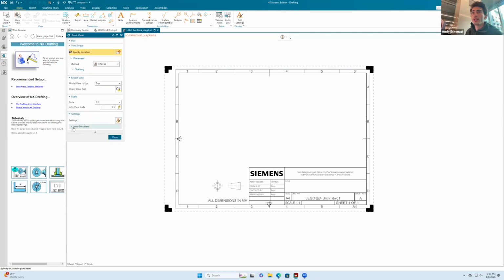Let's look here at the settings. No, that's completely fine. Normally in my other drawing, I had it at 3 by 1, which seemed to be good. Normally when you do drawings, you want to have 3 views: the top and the side. So essentially you have it like this, then like this, and then like this. You're going to have 3 projections. Normally you would also include an isometric view, which shows how it looks in 3D. Those are generally good drawing practices.